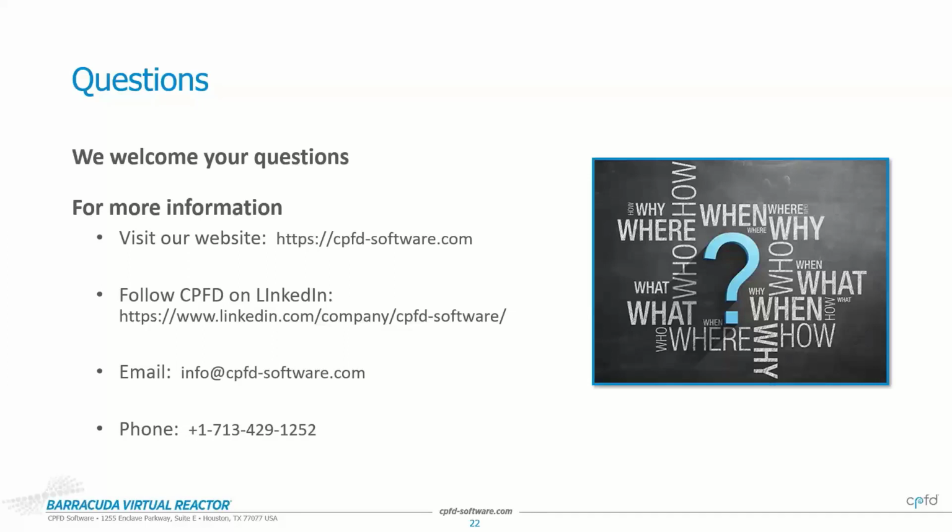Okay, this one's related to what you showed about the different parser variables. It says: with particle position available in user drag, is it possible to find different drag models in different parts of my system? As I read the question, Sam, what comes to mind is perhaps chemical looping combustion, or carbon capture with sorbents processes, where you have a riser that flows through a cyclone down into a bubbling bed, several different beds in different transport regimes.